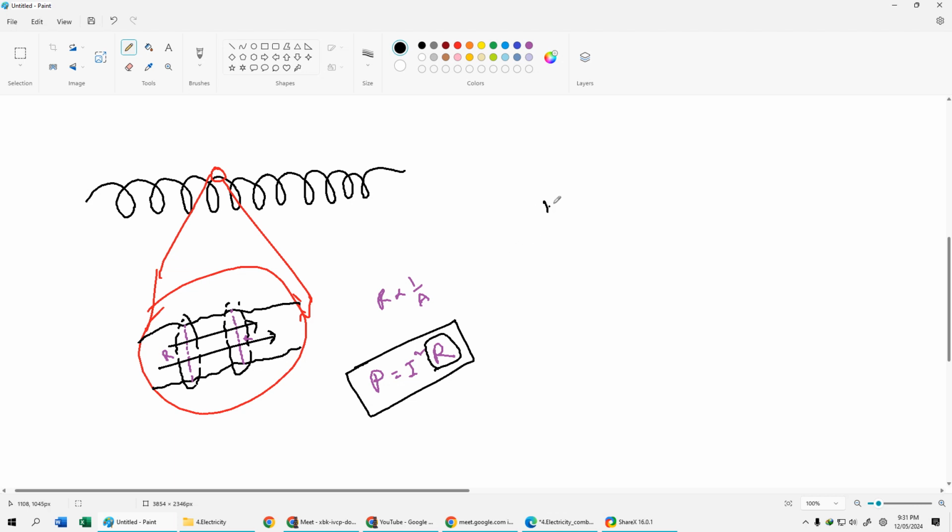For example, if you consider 12 ampere, 12 ampere is the operating current of the bulb as per the question. But if you switch on the device at room temperature with all the voltage, this current is not supposed to be 12 ampere. 12 ampere is the operating current, meaning that when the entire filament lamp was really hot, that's when the current was 12 ampere.